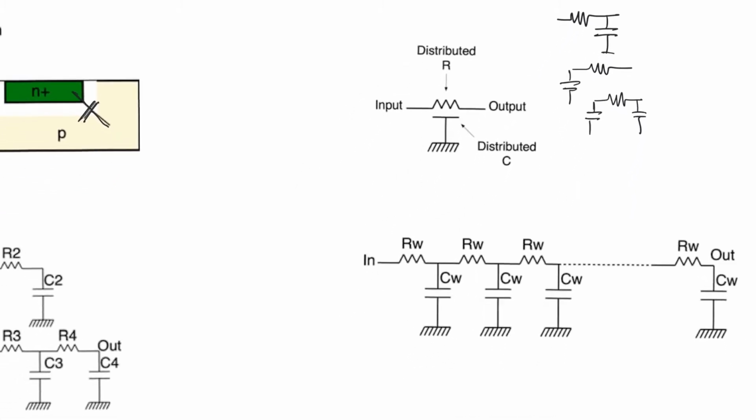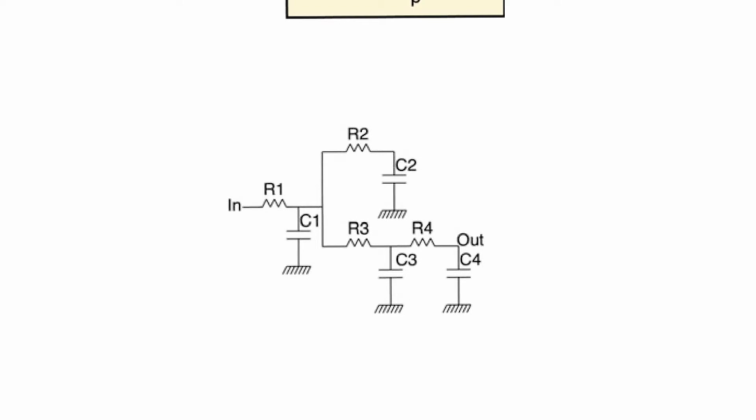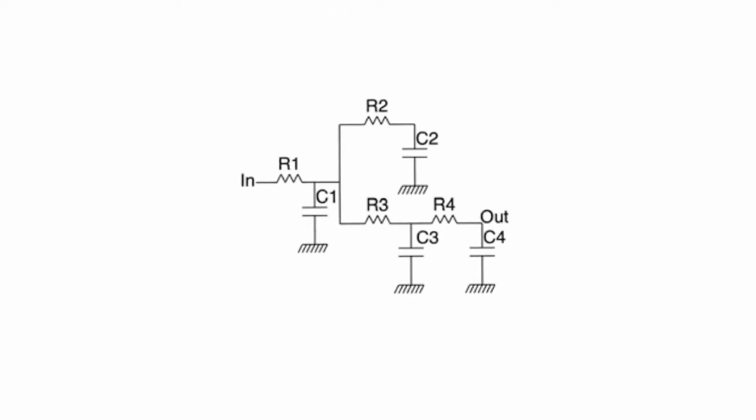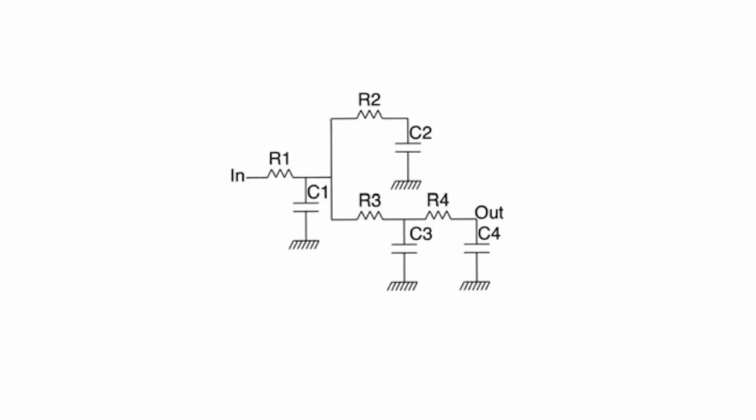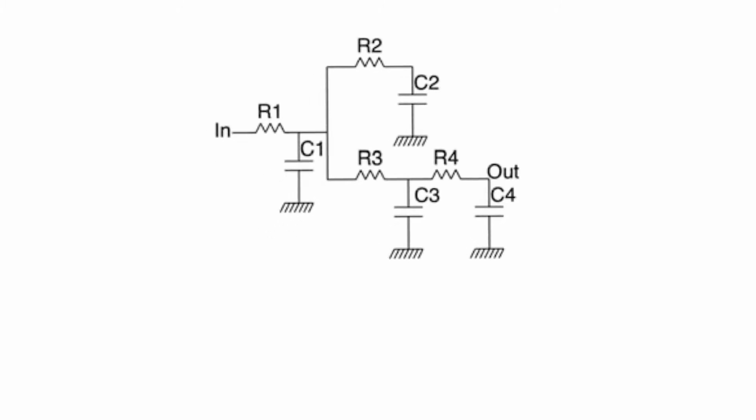So in modules 3 through 6, we dealt with networks which had a single resistance and a single capacitance. We started to talk about having multiple capacitive nodes when we talked about charge sharing, but in the charge sharing model, we always ignored the resistance of transistors. Now, we have to deal with a case where we have multiple capacitances and multiple resistances. And in that case, we can calculate something called the Elmore time constant. The Elmore time constant is a way to calculate a time constant in a network which has multiple capacitive nodes.